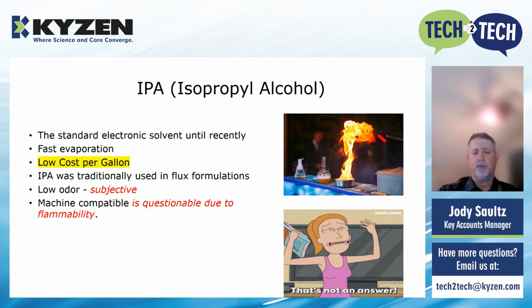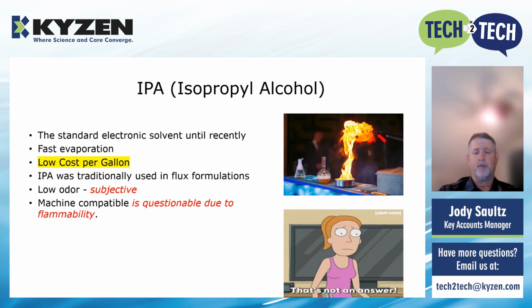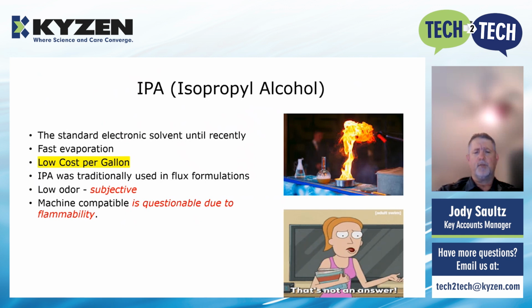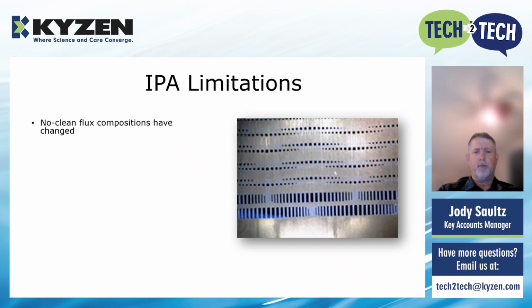IPA was traditionally used in flux formation years ago as well. So in some cases, it really doesn't dissolve certain paste like an engineered chemistry would. And machine compatibility is questionable due to the flammability. So, other IPA limitations: no-clean flux compositions have changed.